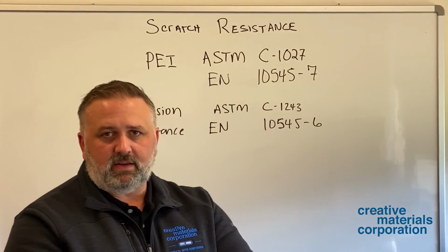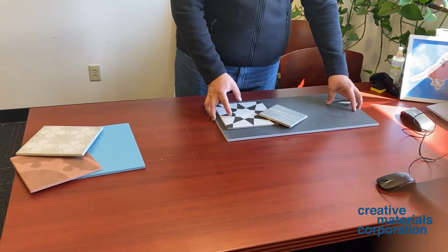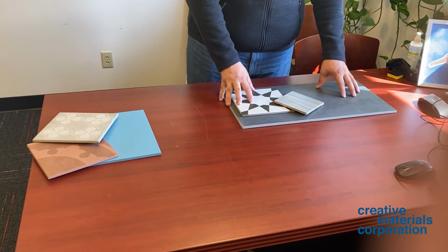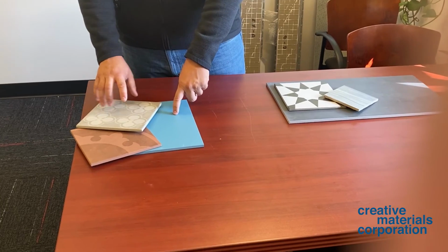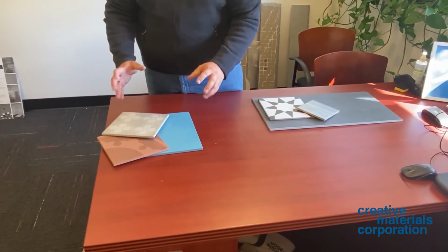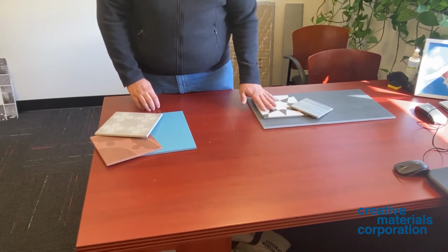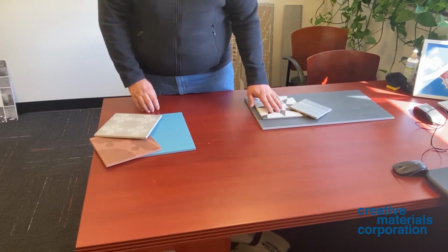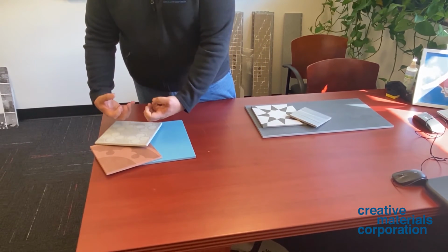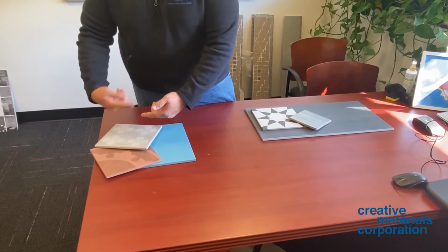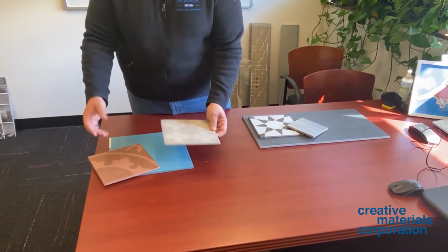So again, looking at the tiles we have on the table here, if you look at our glazed tiles, these tiles here would all use PEI. If you're looking at our through body unglazed, which we'll categorize as unglazed, even though the look here is the same, where this uses a PEI to test the scratch hardness of the glaze, because this glaze is absorbed into the body, you now have to use abrasion resistance to find out when this is going to scratch, if at all.